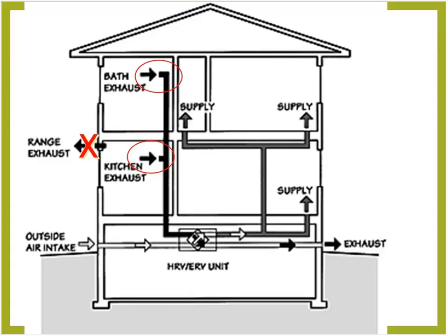The other thing that these systems can do is eliminate more holes. If you remember, you want to work with your client to make sure their range hood is exhausted and that their bath fan is exhausted. It can be really important because those are holes in the house. Not only are they potentially leaking energy, but they're also exhausting the tempered air, so heating and cooling.